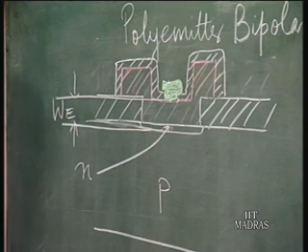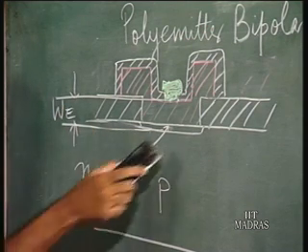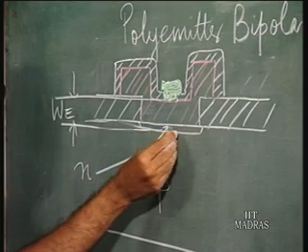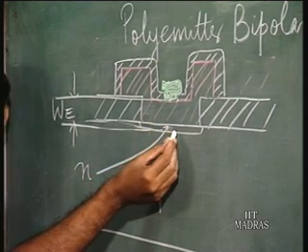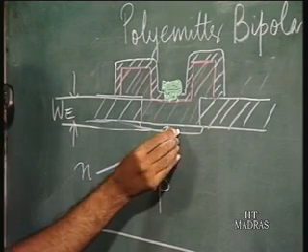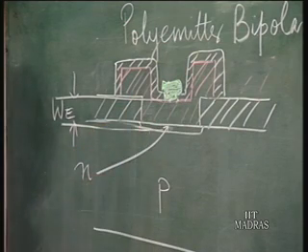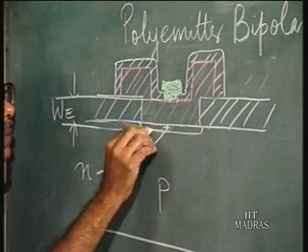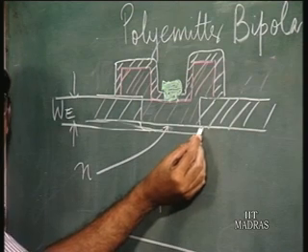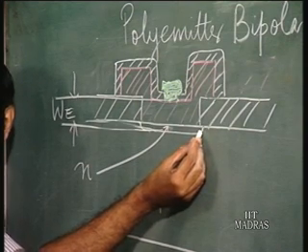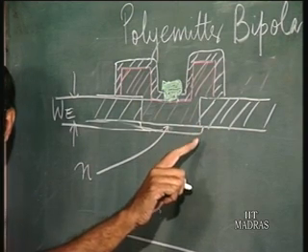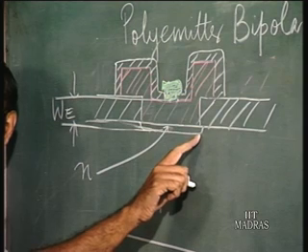All right. That is the total thickness, because the minority carrier concentration in the emitter, which has its peak here, is going to go to 0 at the polysilicon emitter contact, whereas the peripheral capacitance you see is due to this part of the junction here. Okay.